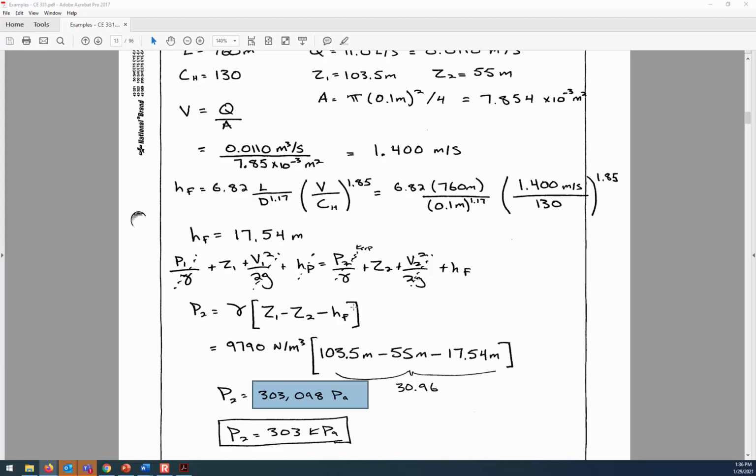So now I think you probably get my point about how velocity head is usually a pretty small component of how much energy is in the system. It certainly makes sense for us to cancel it out in the tank, but even when the water's moving at a pretty good speed, the velocity head is not quite negligible, but certainly the error that's built into using the Hazen-Williams equation, you know, like maybe it's accurate within 3 or 5%.